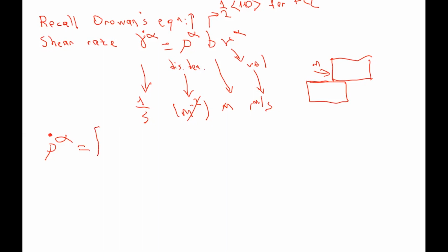And generally, we have one term due to creation and multiplication with the constant K1, dislocation density, let's say alpha, minus, we need to subtract the destruction terms once we have annihilation, K2, and dislocation density squared times the shear rate. This is the formula for dislocation density.